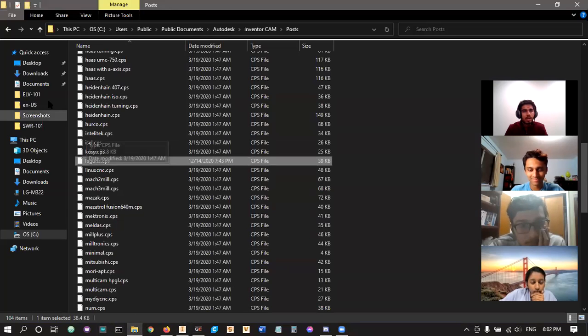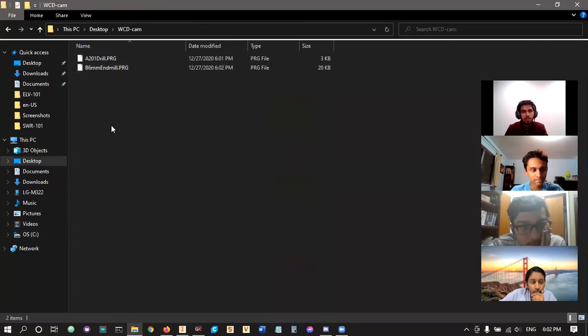Now if I were to hand this folder over to somebody else that didn't know what my part looked like, they could still cut it out, because they just set it up and use a 201 drill. So they go first A, find a 201 drill, use that. Second operation, 6mm end mill, use that. Right, and let's see, there's a chat.